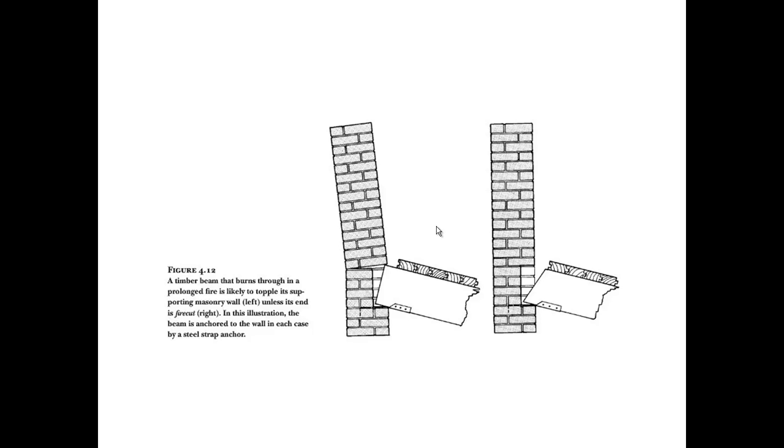And I'm sure some firemen probably lost their lives being crushed by falling brick walls off of these buildings. So a fire cut was developed, so when these beams get put in, they cut this beam at an angle, so if the floor does collapse, the outside wall will still stay intact and structurally sound, so that the masonry may be fine and the interior could still be rebuilt, and that's referred to as a fire cut.